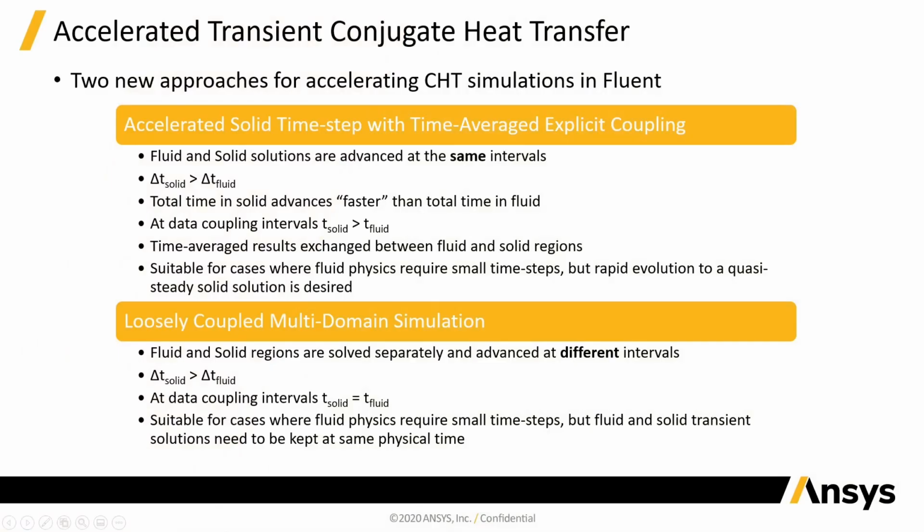So the first thing I'd like to talk about is the problem you have when you've got two very different time scales, one for the fluid, which can be quite short, and one for the solid that can be relatively long. Imagine a combustion problem. You might have to run with milliseconds to capture the fluid dynamics, but your surroundings may take 15 minutes to heat up. If we run with that time step on both of them, it's going to take a very long time to model that heat up. So there are a number of different ways of approaching this, depending how strongly you want to keep the solutions coupled. So the easy way to understand this is skip to the next slide.